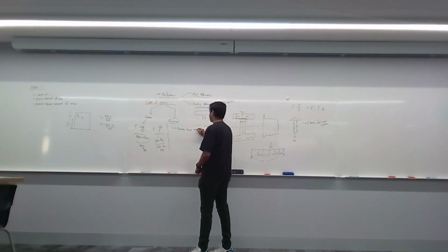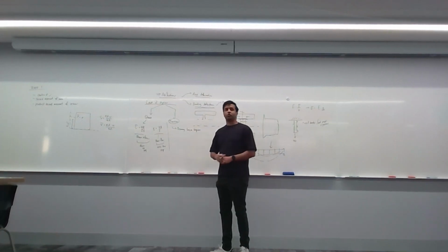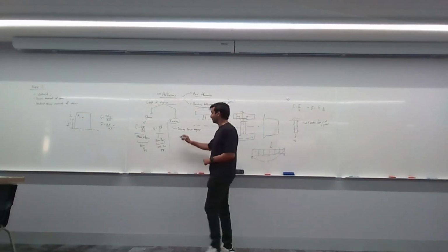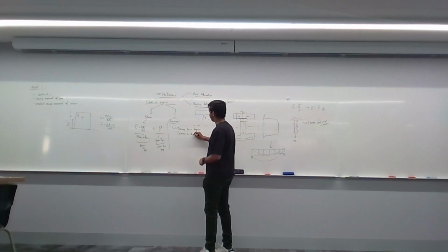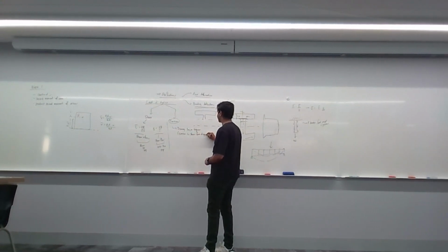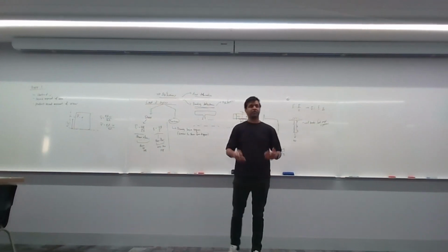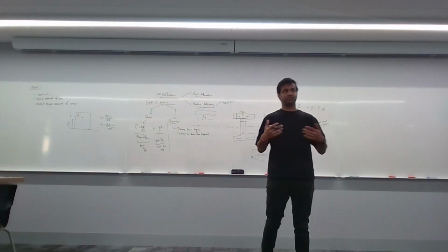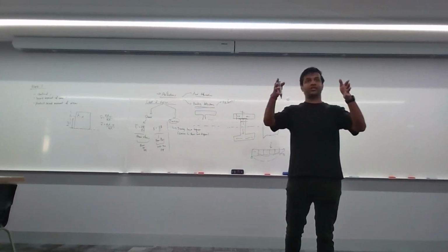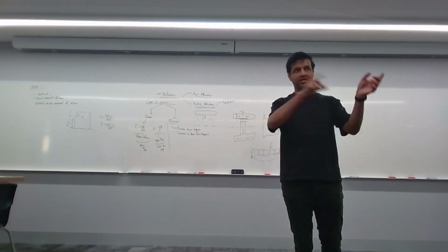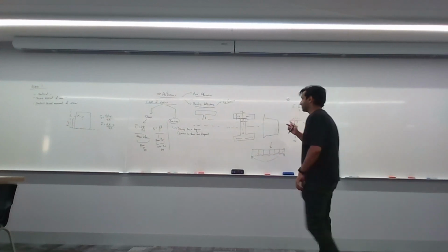The one thing to know is for torsion questions, drawing the torque diagram is similar to a shear force diagram. The concept behind drawing a torque diagram is similar to a shear force diagram. Now have a look at the questions in the workshop. Try them out yourself. That's really important because a torque diagram tells you how much torsion is experienced by a given beam at a particular point. That's the first thing you've got to remember for torsion.